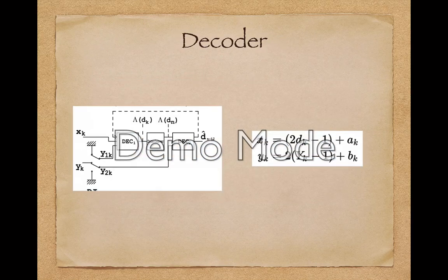So the decoder of the turbo code can be designed in a similar way as we designed the encoder. We need two elementary decoders connected to each other in serial, not like the encoder, where we arrange them in parallel. The structure of the decoder is shown in the left image, and the SK, YK received by the decoder are shown in the right image.